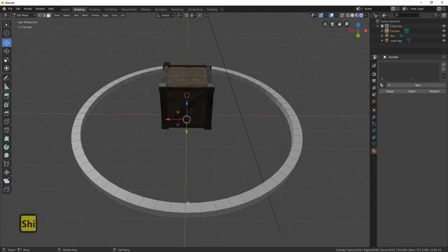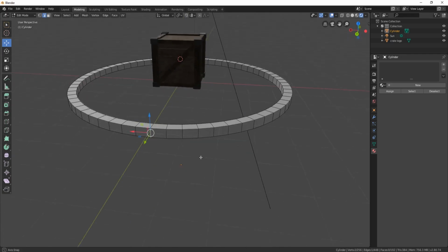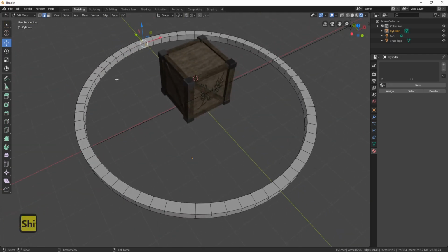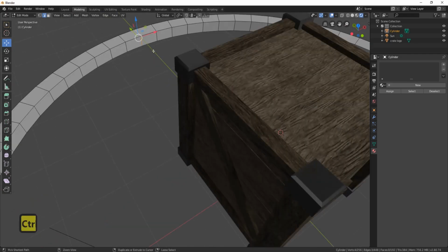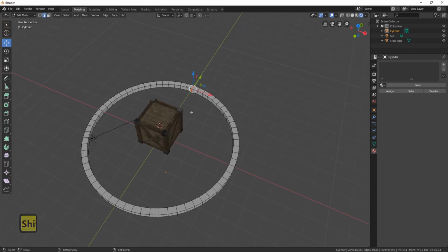So let's go to the back, which is around here. Come to verts, and we'll select these verts going round. So all these going round, as you see. Control E and mark seam, and then I'm left with something like this.